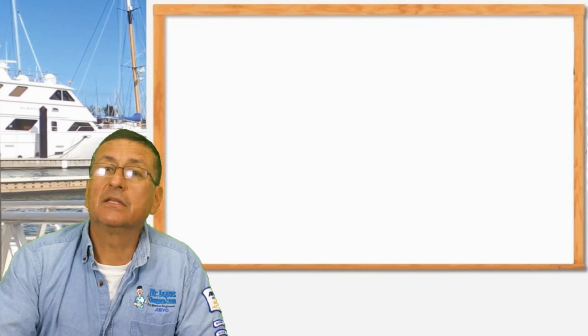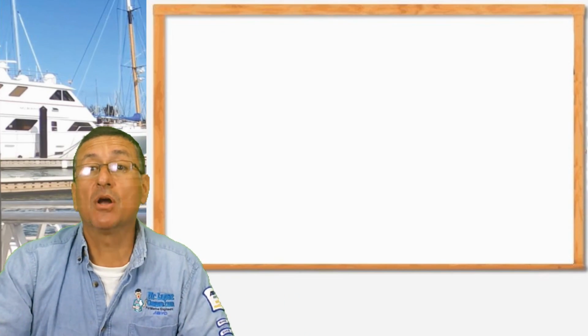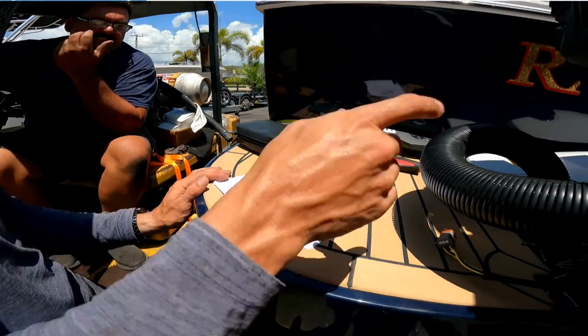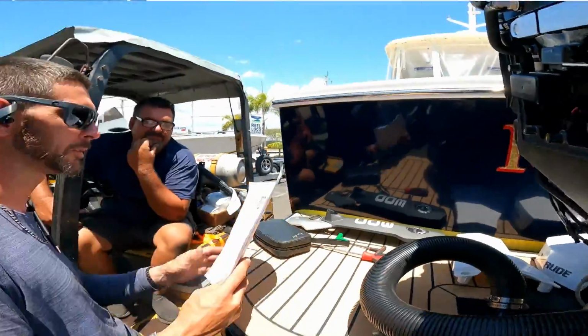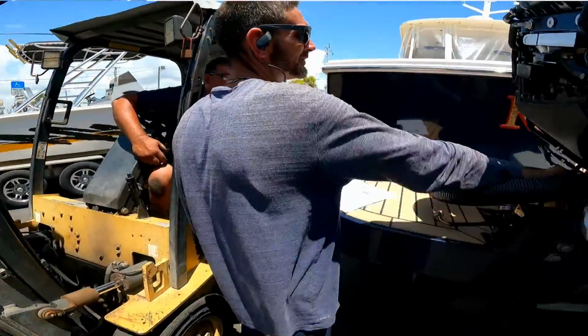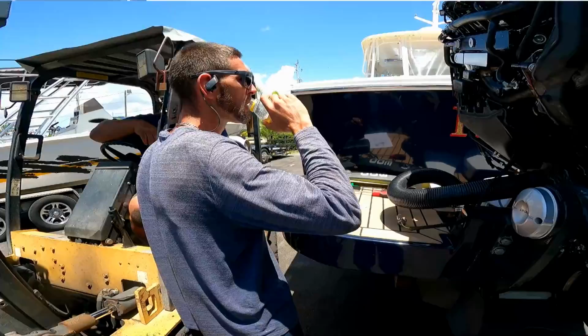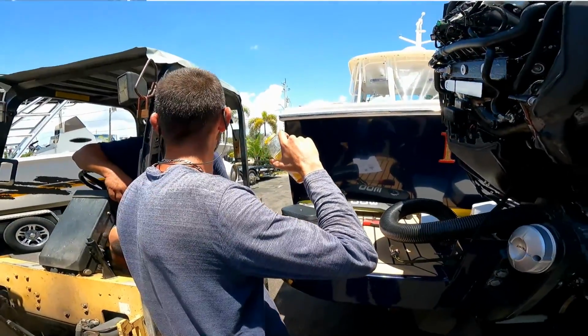In other words, the sensors are okay, the readings are okay, the harness is in good condition. The problem is the module. So it's going to need a module. That's correct. Alright, we are going to change the module and see what happens. We can switch the module.